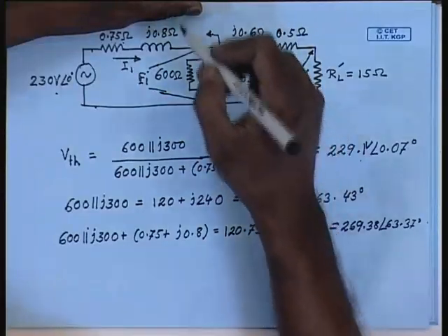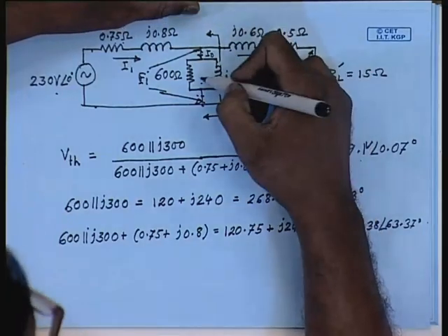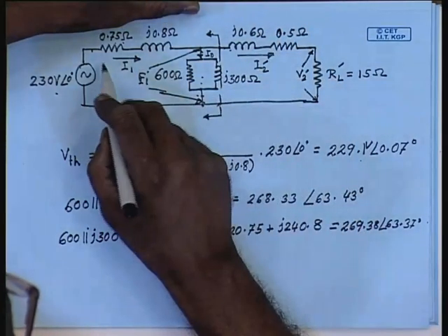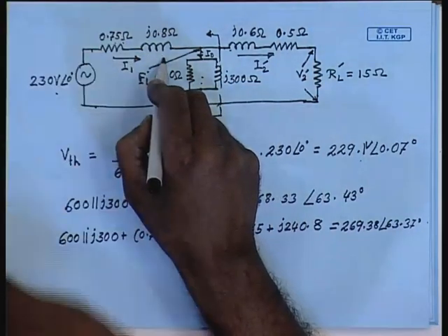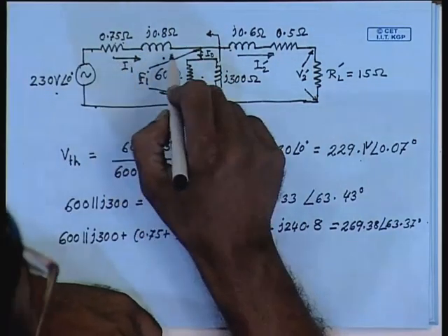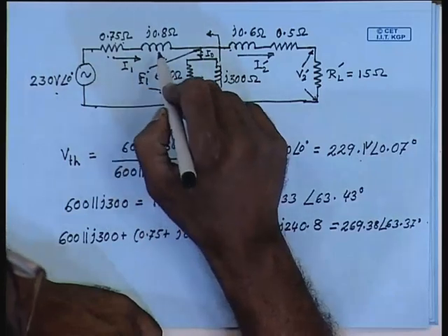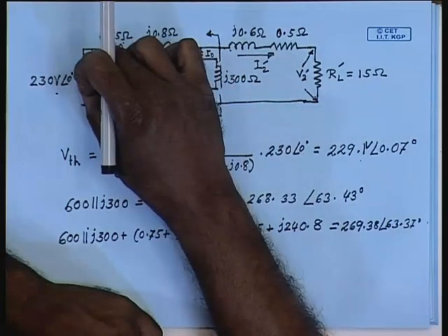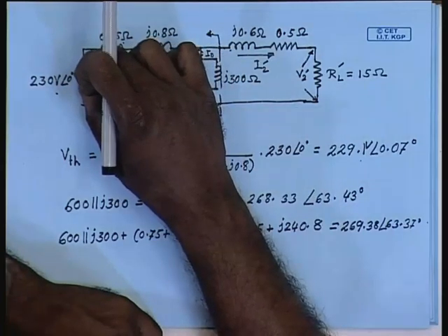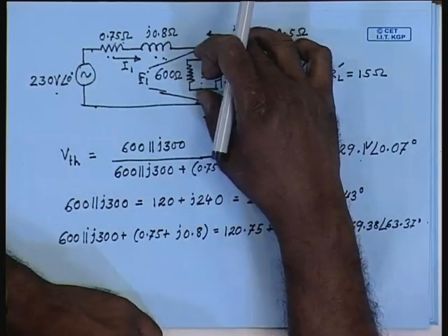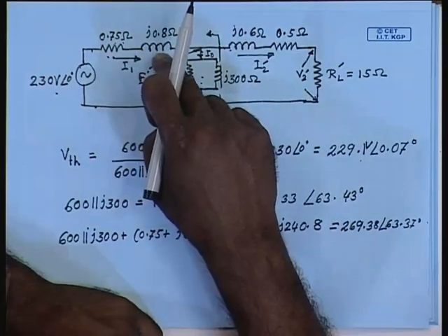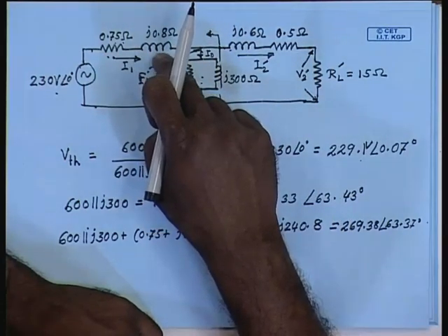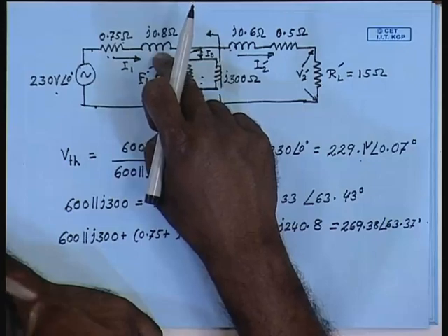The rationale is this: the impedance of the magnetizing branch being much higher than the impedance of the primary winding, that is winding resistance and leakage reactance, the entire applied primary voltage appears almost across the magnetization branch. The drop across the primary impedance is very small even at rated current.